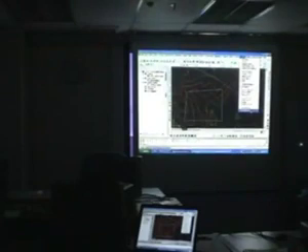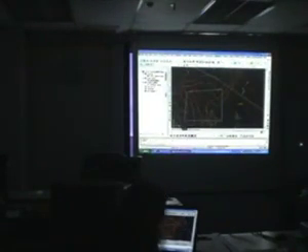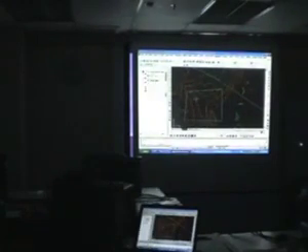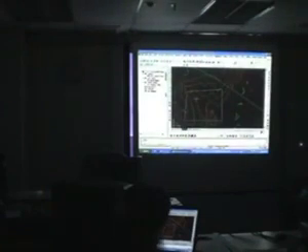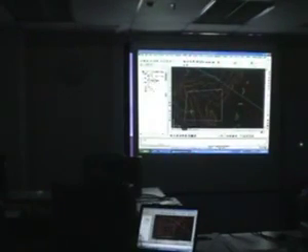There is a very unique function here called track elevation, where if you look at the bottom here, instead of coordinates, it's now been changed to ELEV, elevation. And just by moving my cursor, you can see how the number changes. That indicates the elevation of the original ground level where my cursor is. So now we see it's about 30 odd, 40 something. So I'm going to put this platform perhaps at 35.